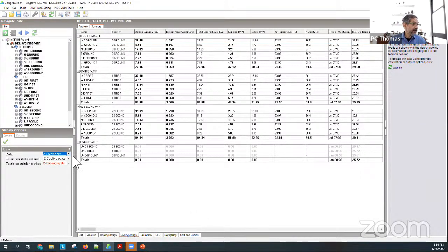But when you are sizing the individual zone registers, so when you are sizing the supply air quantity for each zone, you must look at the non-coincident size. That's when that zone is peaking. That's when that zone requires the most supply air at a fixed temperature. And that's how you take these numbers, okay?